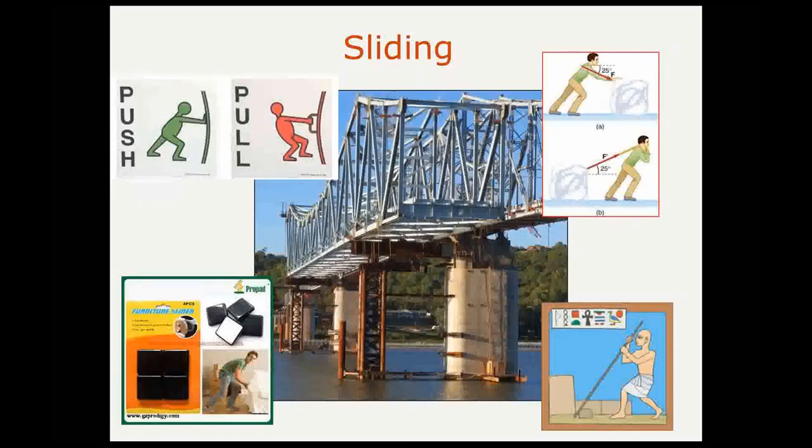When we looked at the slide, we considered a couple different options. We considered pushing the bridge over from the temporary pier, and we considered pulling it from the permanent pier, pulling it over from the temporary pier to the new pier, or to the rehabilitated pier. And both those two methods had different implications as far as forces that would be imparted on both the temporary and the permanent pier. And what we ended up deciding to do was pulling it. We would use a strand jack from the main pier and pull it across from the temporary to the rehabilitated pier.